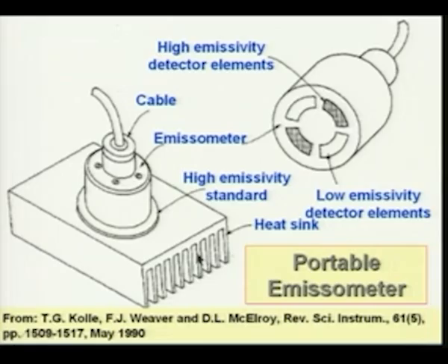The heat sink is to make sure that the sample which I am going to use is going to be at the room temperature. Therefore, the heat sink is going to remove any heat which is falling on it because of the proximity of the heated head. Whatever heat transfer takes place has to be removed quickly, so that the temperature remains more or less fixed at the room temperature value.